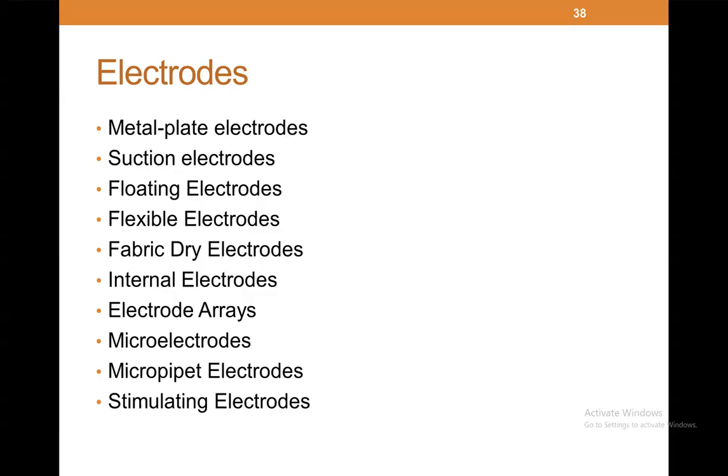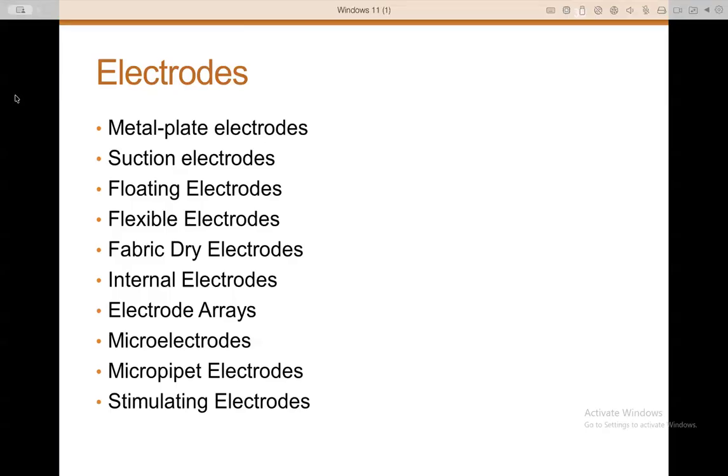Coming to metal versus dry electrodes, they're also metal. In EEG applications, one of the things is you can have those gels. More of the modern technology is to go for dry electrodes, but they're not as good, I shouldn't say that, but practically so far, the ones with the gel actually outperform on longer recordings.